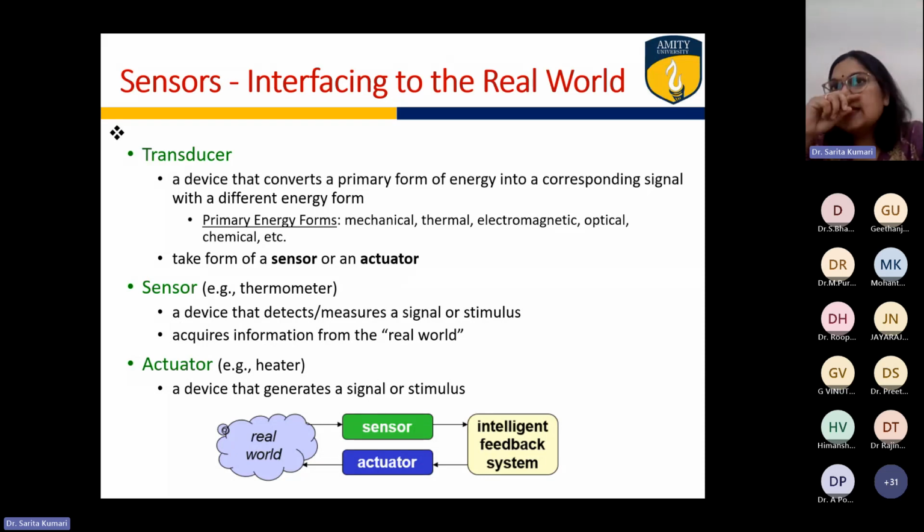In this case, it is a very small round float-type device placed inside the tank, and once the level in the tank goes down, the motor is automatically turned on and the water level increases in the tank. Once the water level increases up to a certain level, the float will detect how much it has filled.